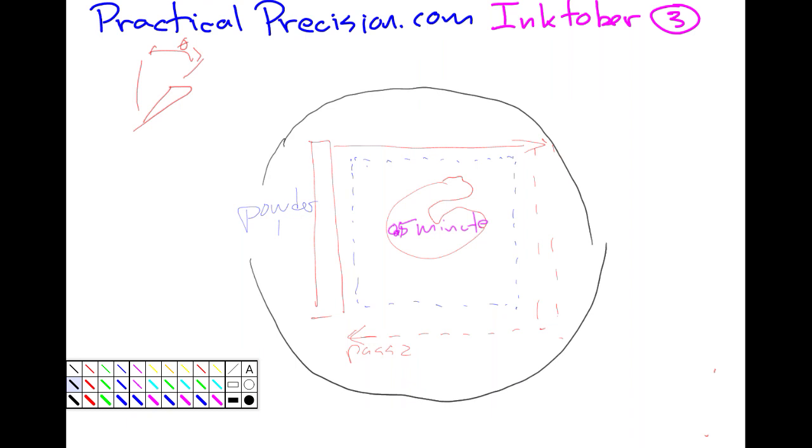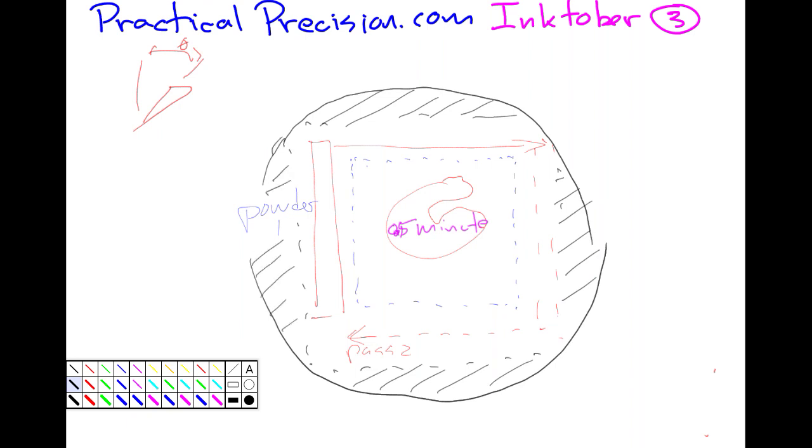Now in this case, though, your circular structure is actually a little bit less space efficient. Because once you've already settled on a rectangular shape, then putting a rectangular structure around it is the most space efficient. And if you were to put a round structure on it, because of the advantages of that symmetry and maybe ease of fabrication, you can make it from a single part, now you have all of this waste space. And that's non-trivial. Again, there are a number of costs associated with a larger machine. One is floor space in a factory.